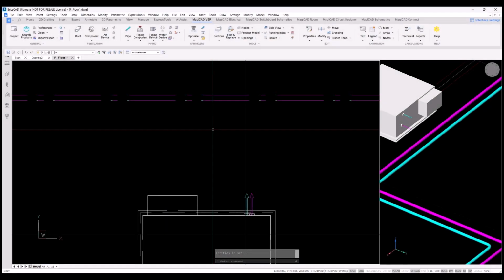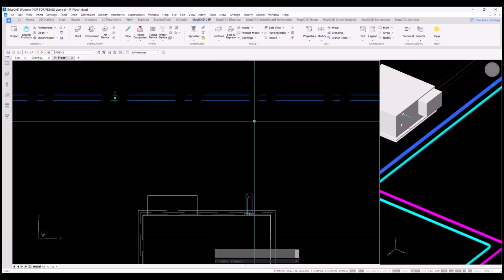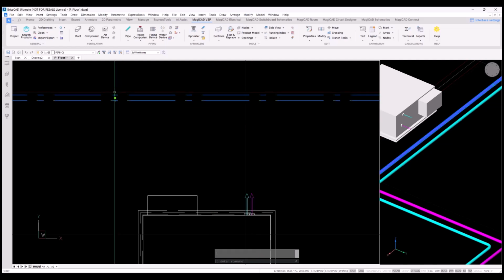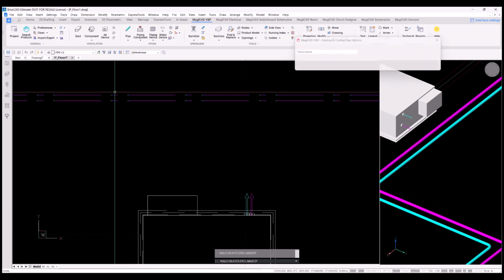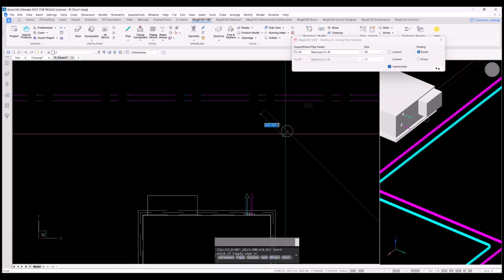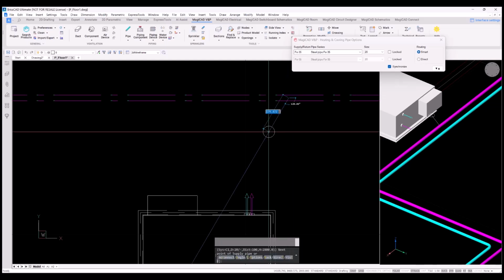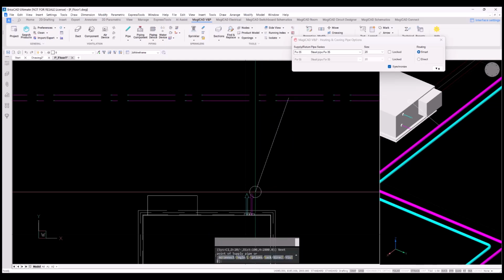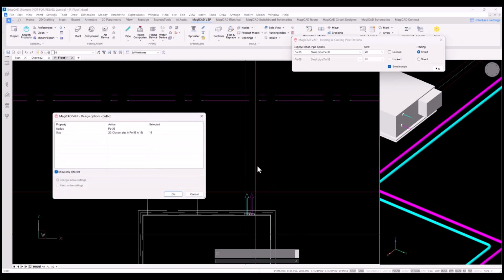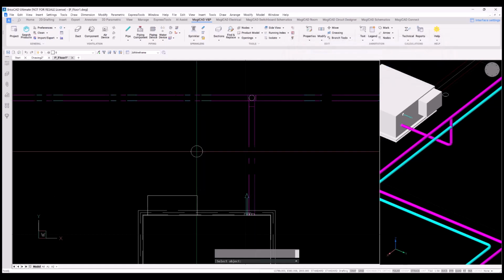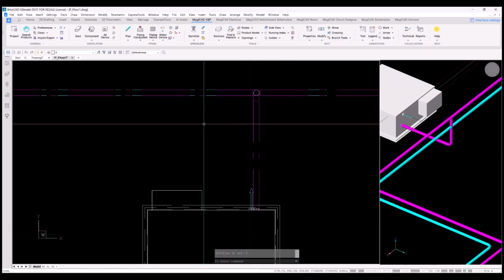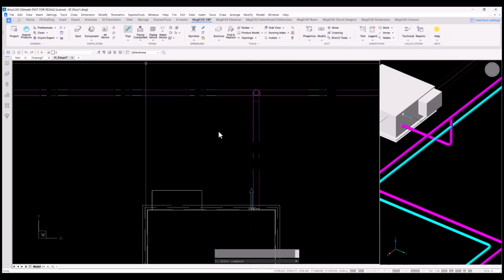Therefore, we can do connections directly from the main pipe to the device. For instance, by clicking on the asterisk handle here, create similar. That is, now we don't have to, having the smart option on, worry about where to click on the main pipe. Just so we click there and click on the connector and OK, it makes the connection. And the same for return.